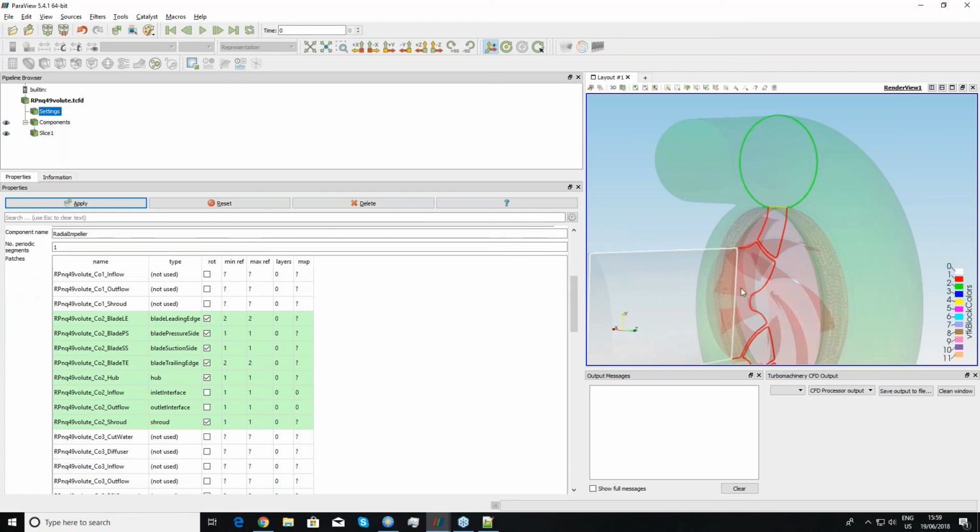Now I am in component 2, and for example, if I would like to have the mixing plane between the volute part and rotor part, I will set it here. For example, five, let's say, axial strips. It will be done here, and now the mixing plane approach will be applied.